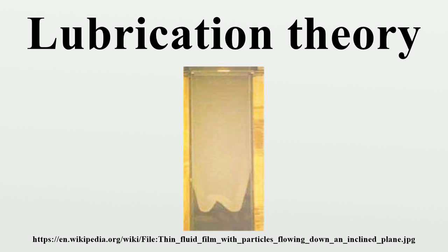Internal flows are those where the fluid is fully bounded. Internal flow lubrication theory has many industrial applications because of its role in the design of fluid bearings. Here a key goal of lubrication theory is to determine the pressure distribution in the fluid volume, and hence the forces on the bearing components. The working fluid in this case is often termed a lubricant.